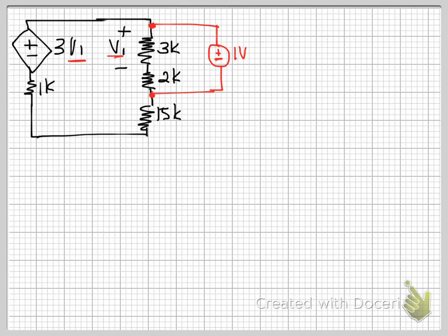So let us now determine our Thevenin resistance. First of all, since we chose a voltage source, we need to determine the current that is flowing through here, IT actually, because the test source shouldn't be IO. IO is output. IT, T. Yeah, looks better.